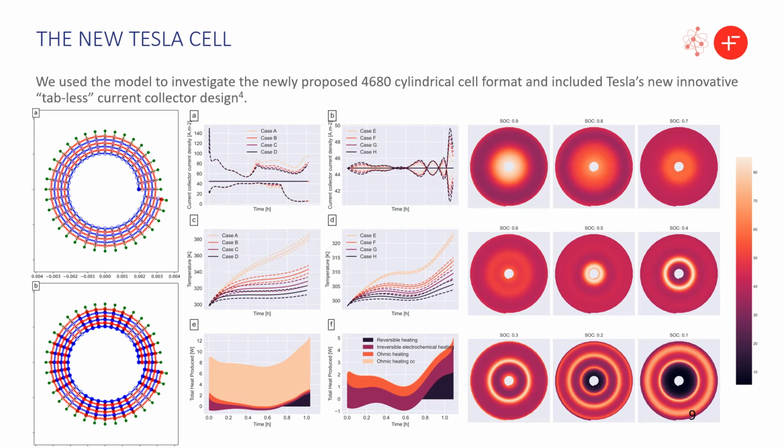It reaches an 80 degree temperature difference above ambient, whereas with the Tesla tabs the ohmic loss in the current collectors is more or less non-existent, and you only have maybe a 25 degree increase over ambient, and that's just for a 1C.